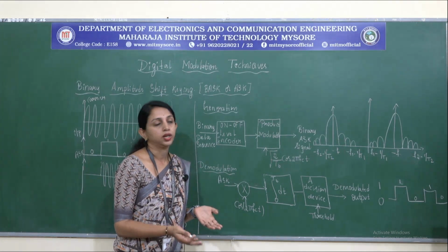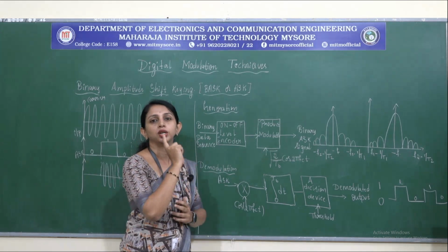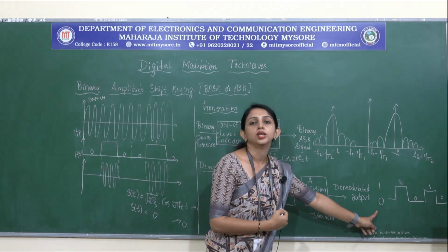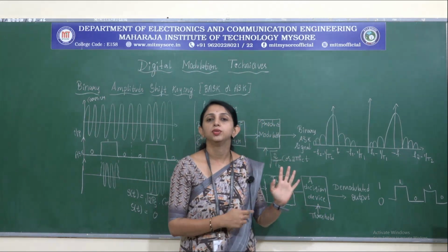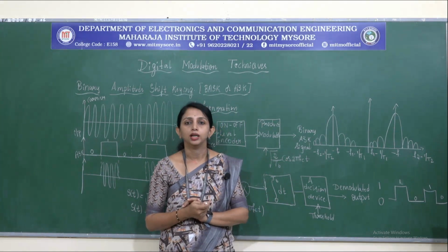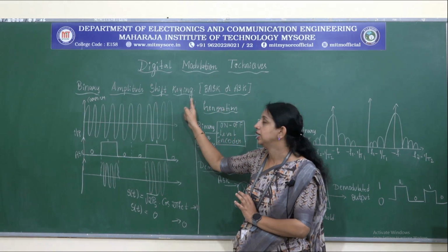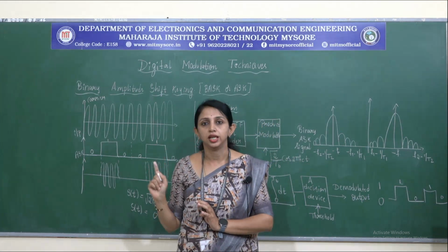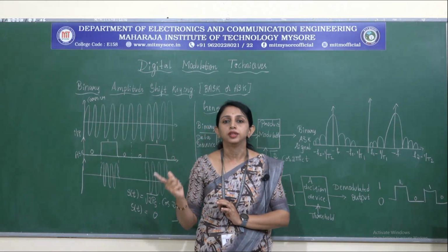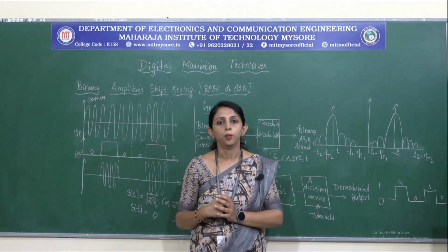Digital output is nothing but the input of the generation. So in a generation circuit, we are going to have a modulated signal. In the demodulation, we are going to have the original signal. So that is the difference between generating and demodulating the amplitude shift keyed values with respect to the first technique, binary amplitude shift keying or amplitude shift keying, which can also be called OOK, that is on off keying, since every time this value will be switching between 0 and 1.